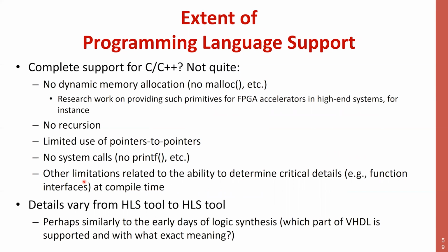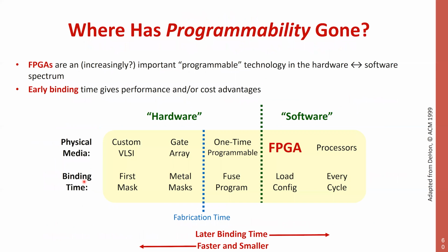You cannot do a malloc because there is no memory to invent. You don't have memory. You have only static allocation because you'll put this in the circuit. And then if you want to malloc 1 gigabyte of RAM, well, it's not there. So you cannot do these kind of things, right? Some others are more limitations, more sort of occasional limitations.